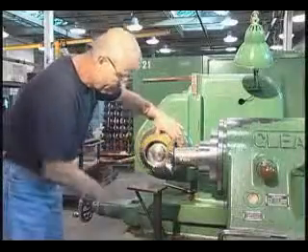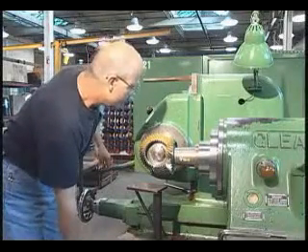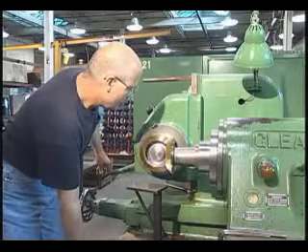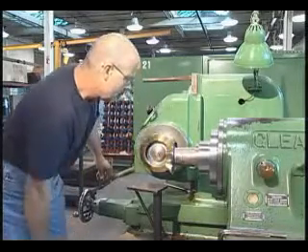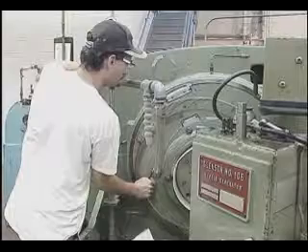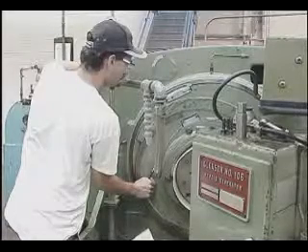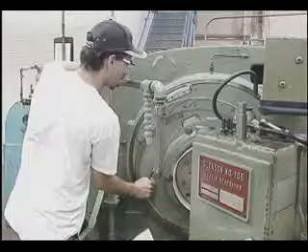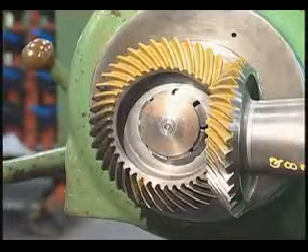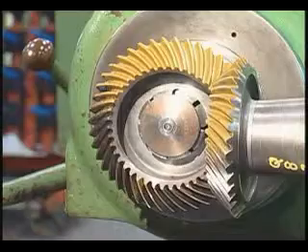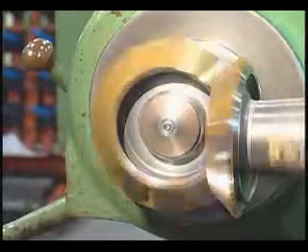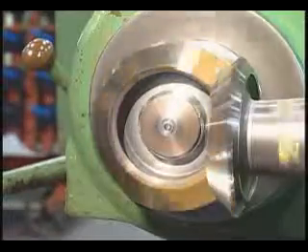When the gear and its mating part are finished, they are run together in a tester. More often than not, the contact pattern will not be correct in this first attempt, and this requires going back and changing the settings on the gear tooth cutter and grinder, then producing a new gear and pinion. The parts are checked again. This trial and error process can continue through many cycles until the best educated guess for contact pattern location is achieved.